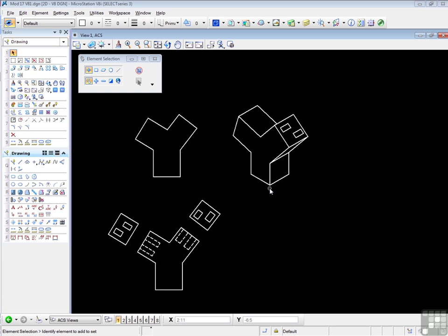The difference between an ACS and a rotated view is that the ACS does not require the view to be rotated for the coordinate orientation to change. And you'll find that AccuDraw also plays a very large part in working with an ACS. All very confusing? Don't blame you. Let's try this simple example to see the system at work.